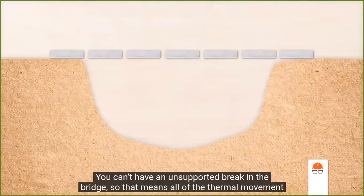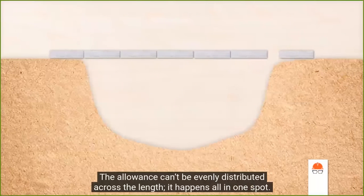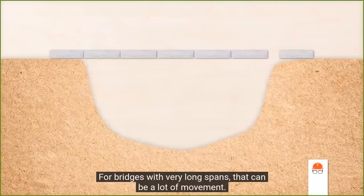You can't have an unsupported break in the bridge, so that means all the thermal movement happens at the supports. The allowance can't be evenly distributed across the length. It happens all in one spot. For bridges with very long spans, that can be a lot of movement.